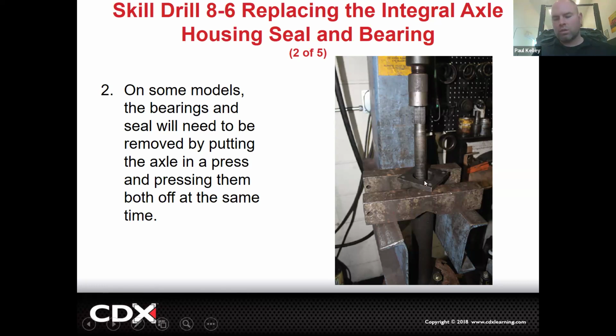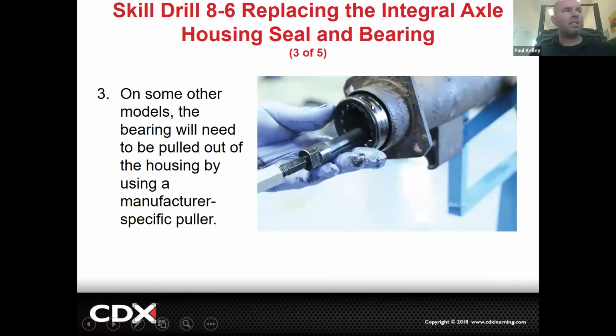So this is one of the tools used. This is the easy semi-float or non-floating. You see the slide hammer hooks the edge of the race and you just pop it out. Much, much easier on the domestic style.